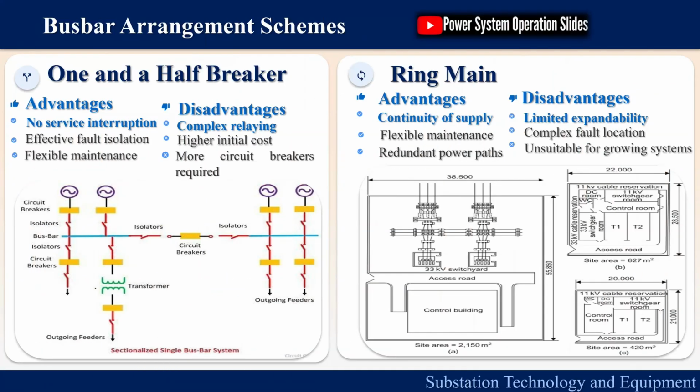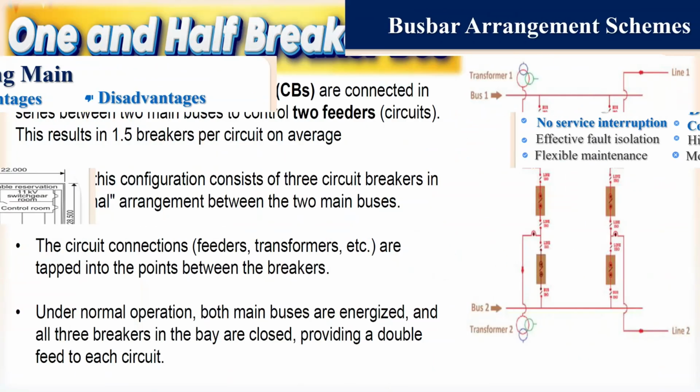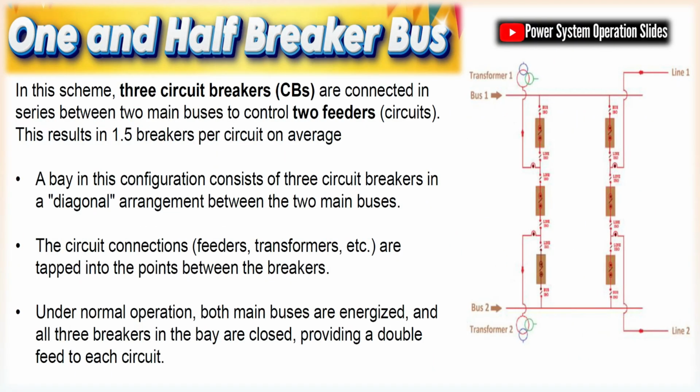Busbar. A busbar distributes power between incoming sources and outgoing feeders. It supports multiple configurations for reliability, flexibility, and maintenance. Its design is central to substation operability. Busbar types: AIS, GIS, enclosed.